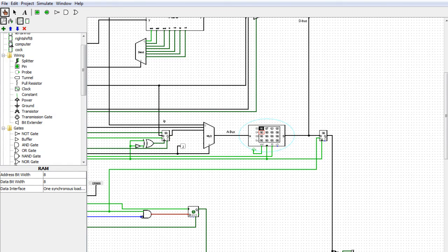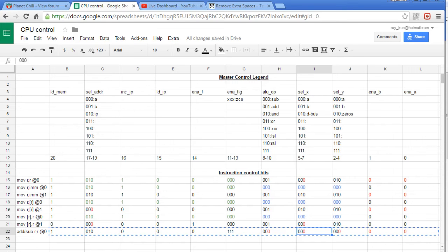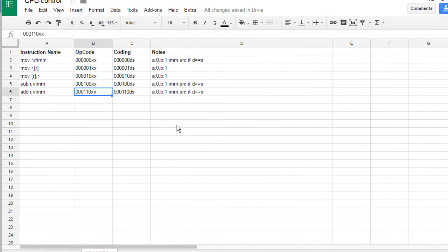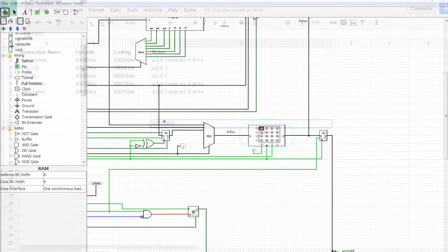I'm not going to do this in my head. I'm going to go to Chrome, opcodes. Let's see here. So, that would be a big 0, 0, 0, 1. Subtraction is 0. Then we just put a 0 in here, and we want destination is A minus B. So this is 1, 1. 1, 1 hexadecimal. All right, let's try that out.